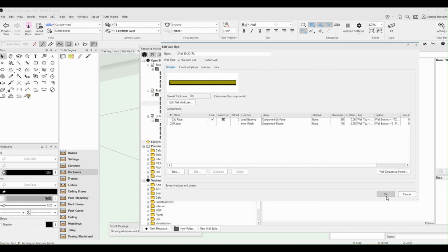And just as a general note, all of the wall styles will be created to have that consideration. So all of your face brickwork is assumed to go down to your footing, and that includes your rendered wall. So there is actually a vertically cored external that will go down -2 to your footings, but the vertically cored internal will stay at 0 at the bottom.